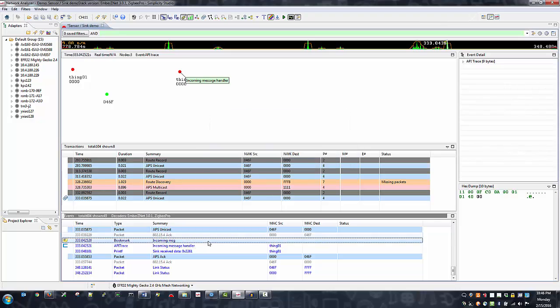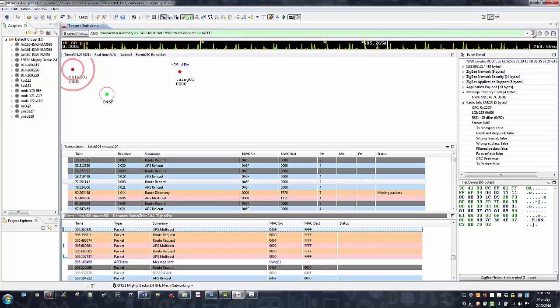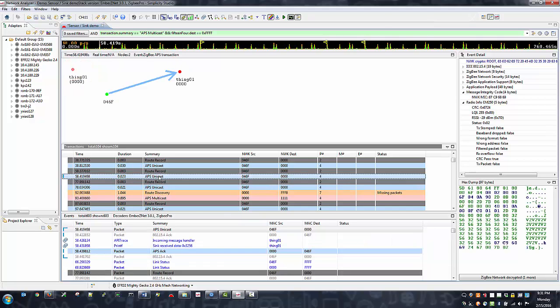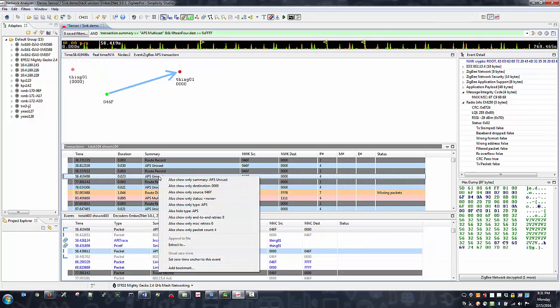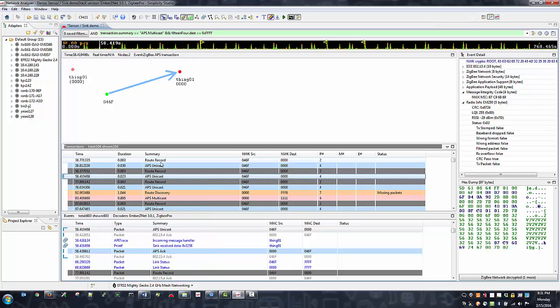But Simplicity Studio's Network Analyzer does more than just examine packets. It can also record software-based debug activity for the firmware on your embedded networking device, allowing application developers a glimpse into which firmware events correlate closely in time with certain network-related events and transactions, which can be a big help in shedding light on why a certain activity occurred or why it had a particular outcome.